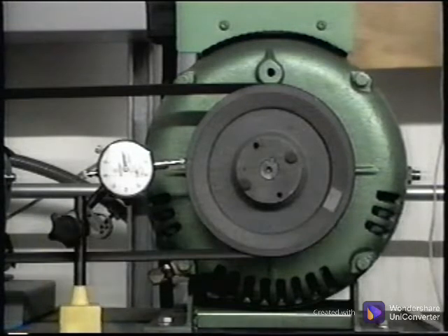A sheave with excessive runout can exhibit characteristics of unbalance on a machine. The eccentric tolerance on the sheave combined with belt variations may be as much as a 1/4 inch per foot of sheave diameter. Replace sheaves with excessive runout. Do not rule out the sheave as it may be the source of the machine's unbalance. Use these 7 pre-balancing checks to maximize the effect of balancing and avoid going in circles. Don't try to solve other problems through balancing.